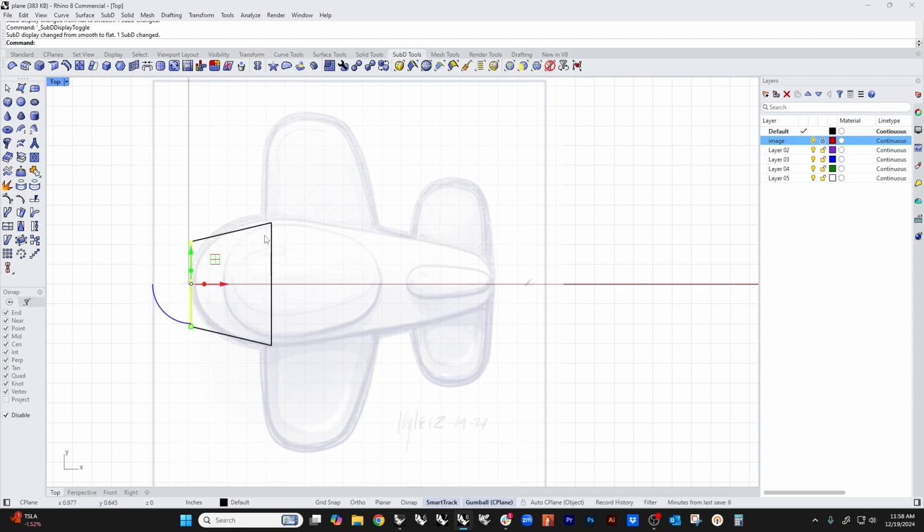Now, we're losing the detail in the back because there's not enough stuff here to make this next shape. So we'll take care of that next. So shift control click on an edge. There's an extrude dot on the Gumball. You're just going to pull that out to about halfway,